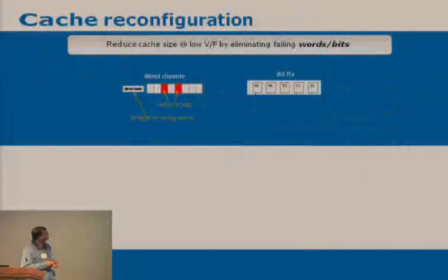When you go to low frequency mode, your DRAM looks much closer in terms of number of clock cycles. So you can live with a fewer or smaller cache size without giving up too much performance. In low frequency mode, you're limited in voltage scaling with the cache. So if you reduce the cache size, then you can scale the voltage a little further when you get into low frequency without really impacting the architectural performance.